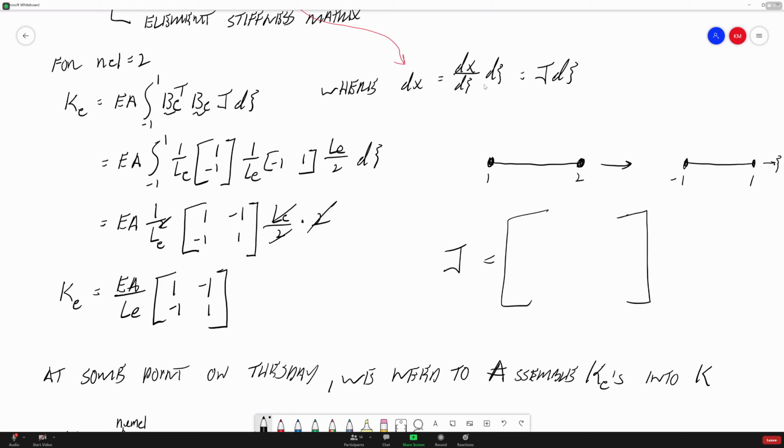So you would have, like a D, I'm just making something up, this could be like a D X1 over D C1 or something, and then D X1 over D C2 or something. It's these partials that fill in this matrix, but it has to do with this mapping from an X coordinate system to this C space at the elemental level. But it's taking the partial derivative of it, which, if we remember, what is the partial derivative?